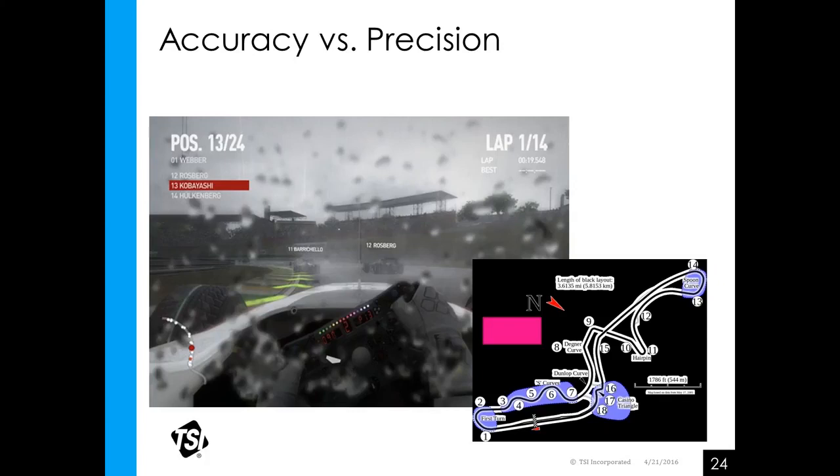Maybe we should define accuracy as the amount of error as measured from the true value, what the actual true value really is. Precision should be defined as any deviation of any one of those individual measurements from their average. And these measurements don't reveal either bias or constant error present in every one of the measurements. Meaning sensors and instruments wear over time, i.e. they drift over time. So that needs to be taken into account.